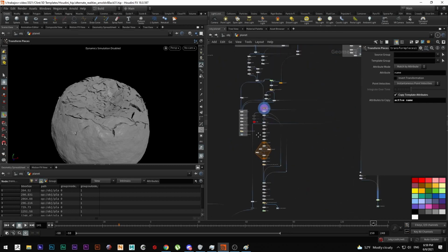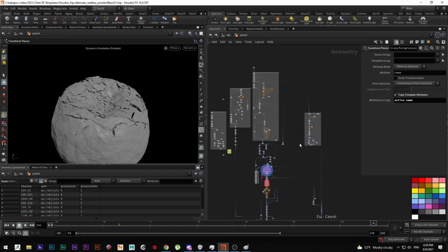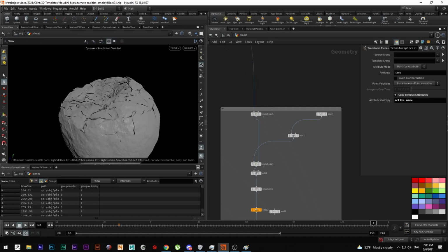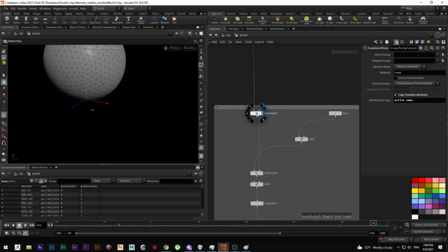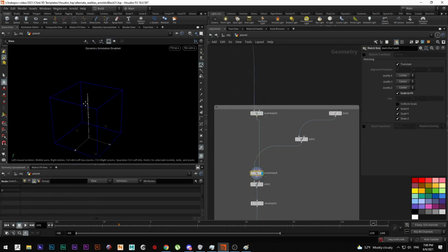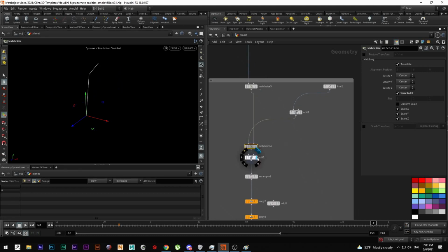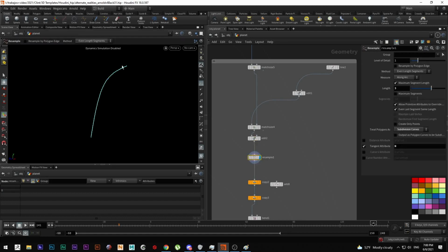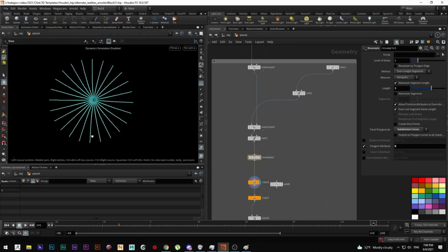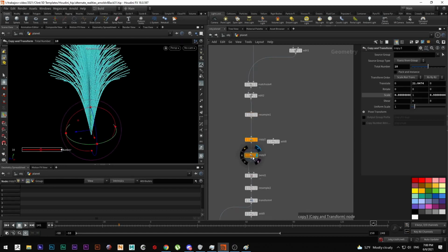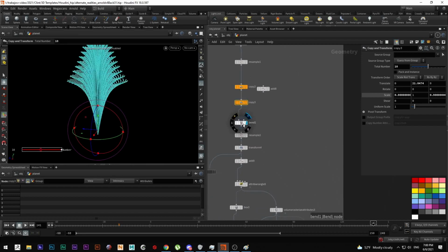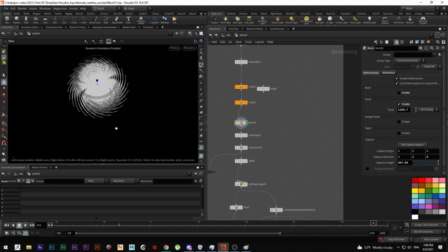So, where is the smoke? I have tons of notes here. First of all, I want to create some smoke going on the inner parts of the planet, but I also want to have some lines to create a tornado or a vortex velocity field. So I edited the points like this. I resampled this to make it more curved, and I copied to create this shape. I also copied it again with a copy transform to create like a tree, let's say, and I bended it like this, so it's swirling.